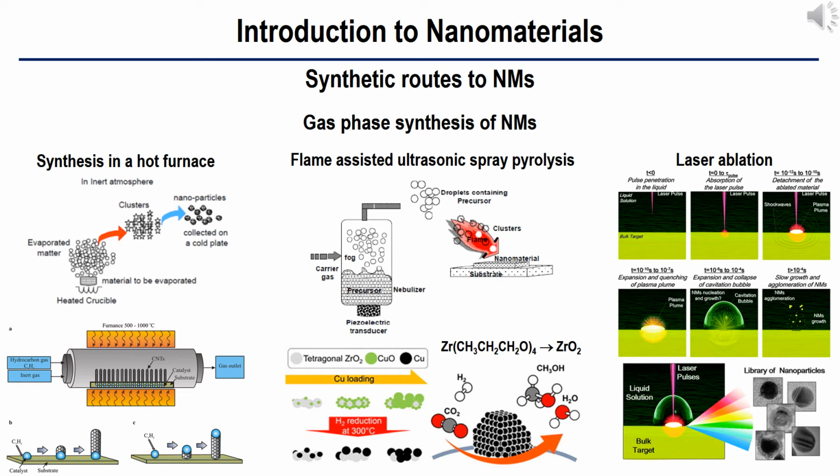Energy is normally introduced into the precursor by arc heating, electron beam heating or Joule heating. The atoms are evaporated into an atmosphere, which is either inert gases or reactive precursors. To carry out reactive synthesis, materials with very low vapor pressure have to be fed into the furnace in the form of a suitable precursor such as organometallics, which decompose in the furnace to produce a condensable material. The hot atoms of the evaporated matter lose energy by collision with the atoms of the cold gas and undergo condensation into small clusters via homogeneous nucleation.